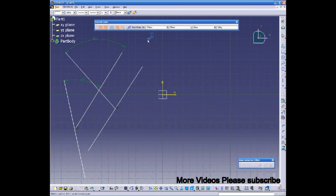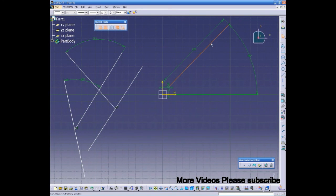As you see, the Sketch Tools toolbar now displays values for defining the line. Type for the start point h equals 10, v equals 12, and press Enter to validate each value. Type in the endpoint field L equals 125, A equals 45, and press Enter each time. The line is created.